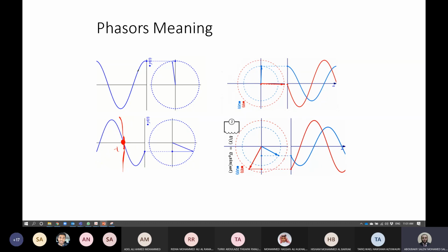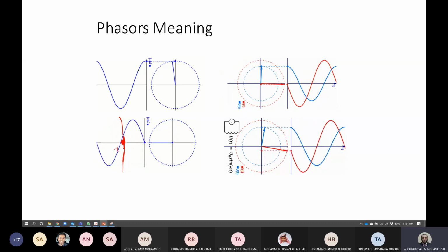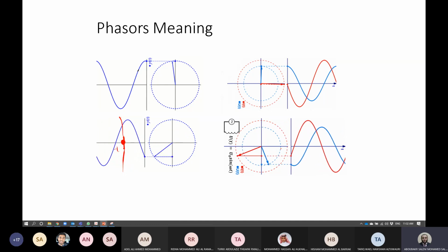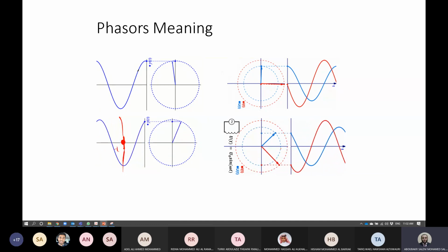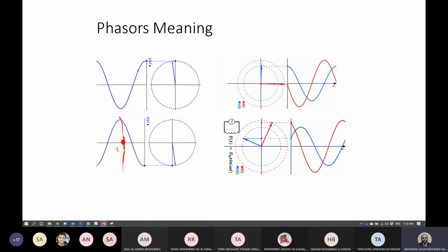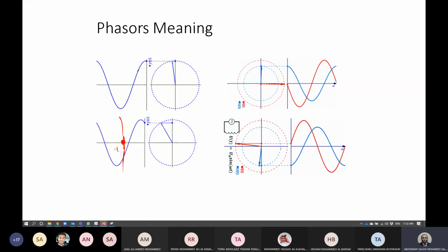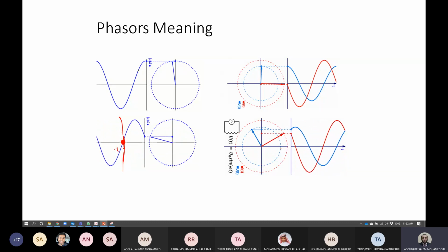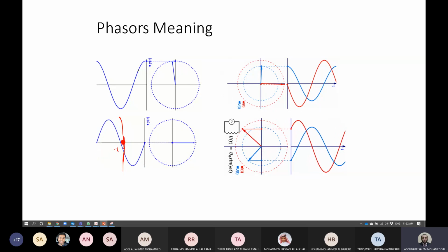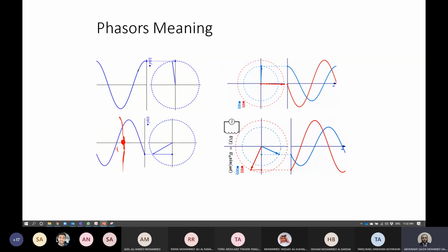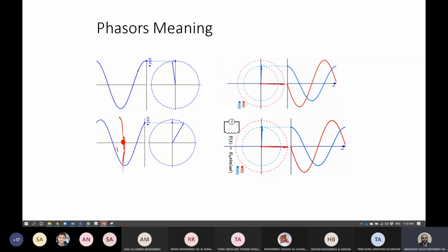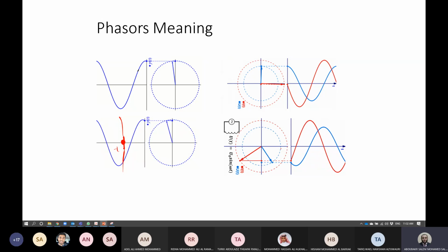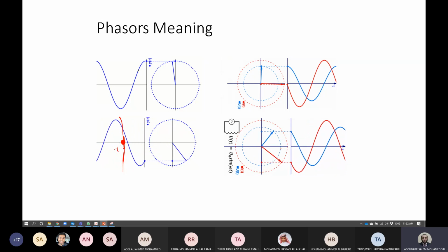So if we move with the rotating frame now, it will be very easy for you to make any calculations. The idea is we need just to change the reference frame, شباب, to simplify the mathematical model of the induction motor. This will be very helpful in control and computation. Because finally, any computation in the control technique will be implemented in a digital controller. So if the code is large, it will take a lot of memory. If the code is large, it will also take more time to be executed. And also, if the results are very huge numbers, it will need high memory and long time for calculations.